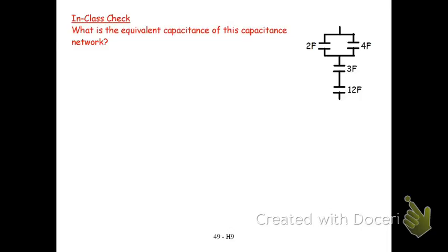They get a bit more interesting. So this is a bit of it's in parallel and a bit of it's in series. And this is a little bit like we did with circuits, where you've got to know your way in. This is unambiguously in parallel with the 2 is unambiguously in parallel with the 4. But is the 3 in series with only the 2? Well, no, it's kind of in series with the 4 as well. So pick the unambiguous bit. And we just start off and you just do this. It's just a bit laborious. Math is not hard. It's just laborious and it's easy to make a slip on it.